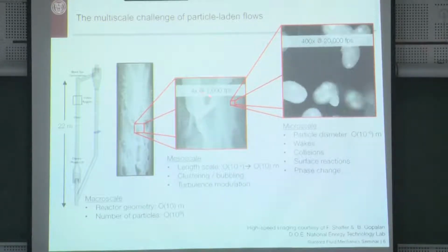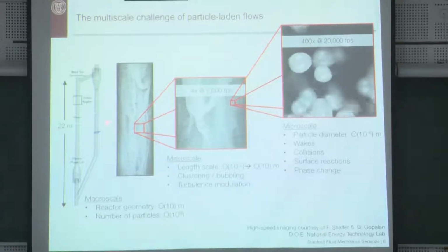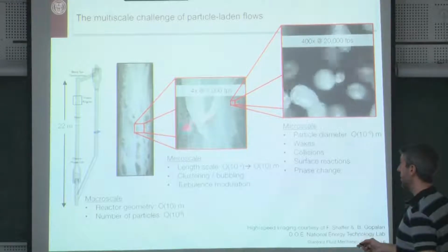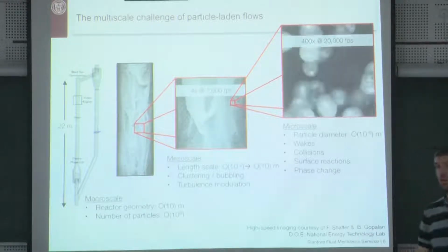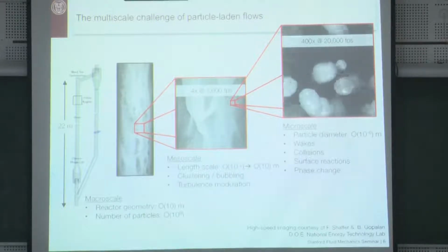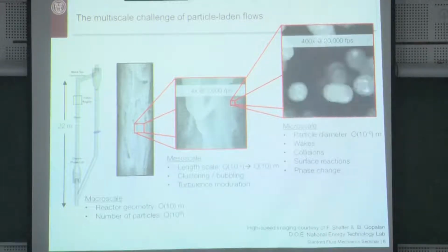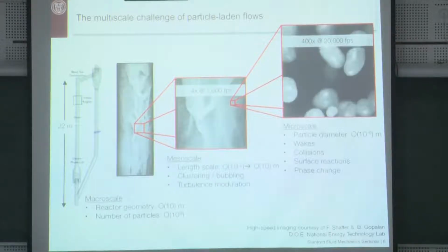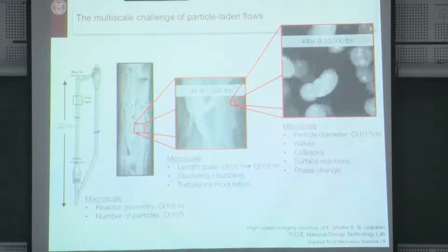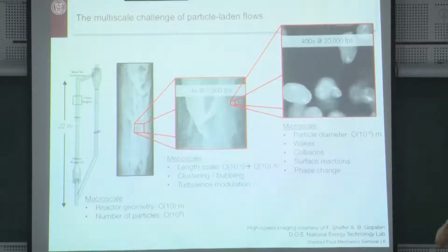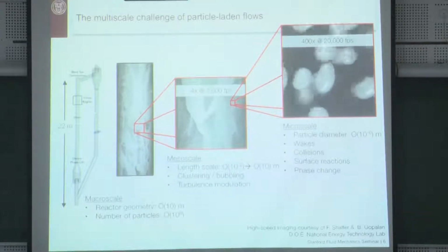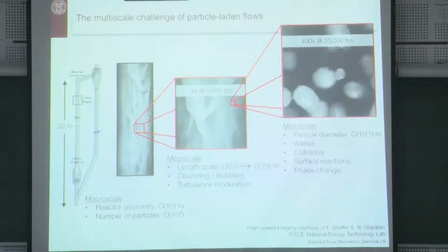Those length scales extend over a pretty wide range, in fact, all the way up to the width of the reactor, but these dense regions here organize on the scale of at least 10 particles, 100 particle diameters, something like this. This is the scale that will most directly influence the flow field. It is on that scale that we have those dense chunks of particles falling and pushing the fluid out of the way. This is where most of the feedback into the fluid phase will take place.